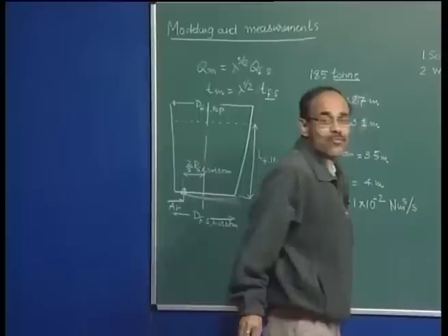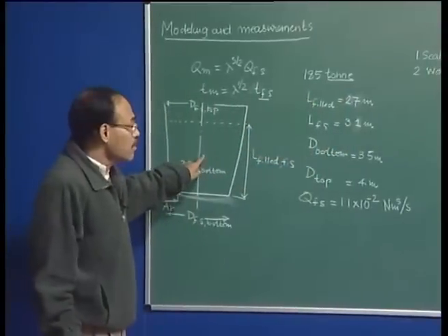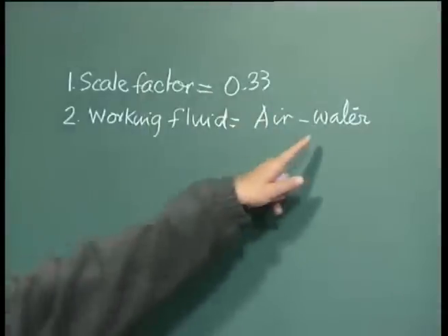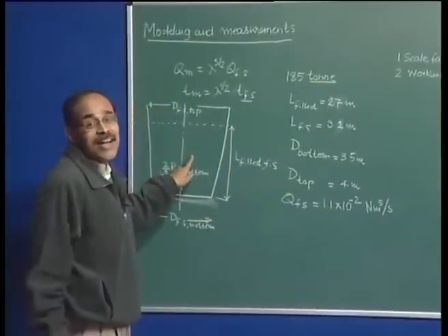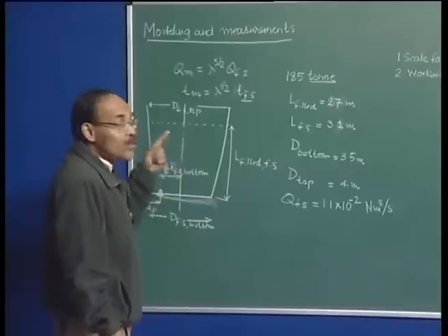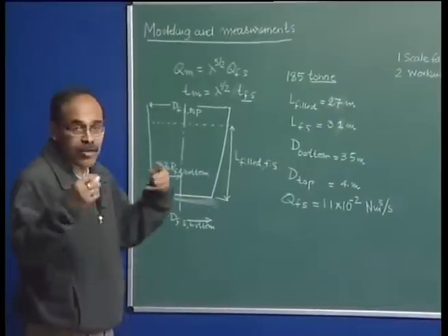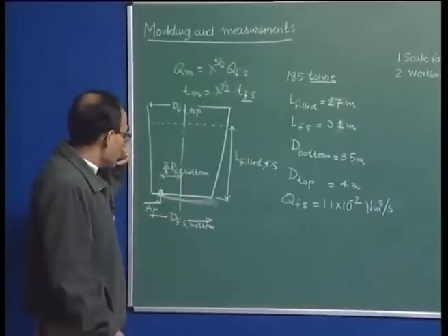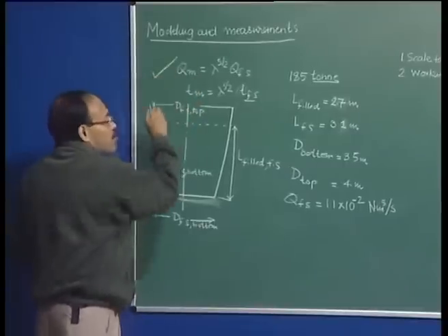So, my bulk liquid is water instead of steel, and as I have indicated earlier, the kinematic viscosity of water and steel are nearly identical. So, we will not be able to respect Reynolds and Froude similarity simultaneously, and we have assumed already, or we will consider in general, that phenomena in steel making systems are Froude dominated.